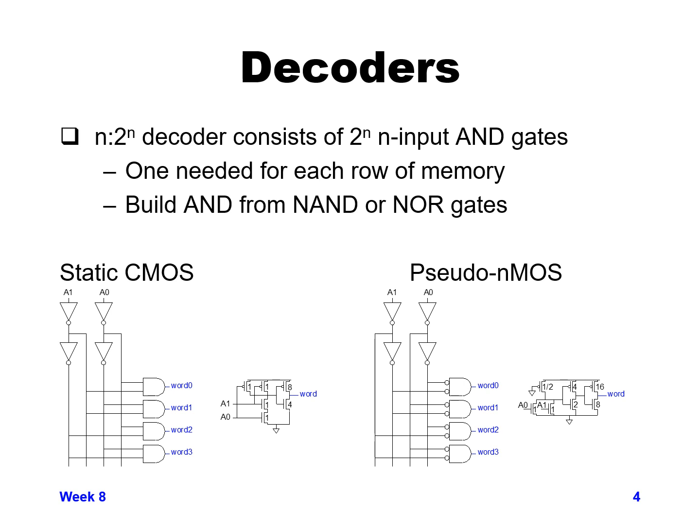We need 2-input AND gates, and then we need 1 AND gate for each row of memory, and we can build those AND gates either from a NAND function or from a NOR gate function, depending on if we do a NOT OR function. So down below, shown are 2 different ways of doing it.